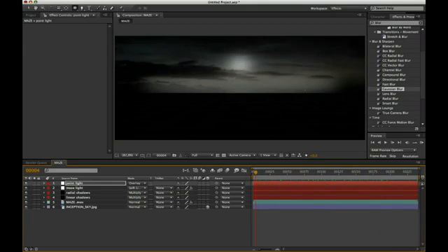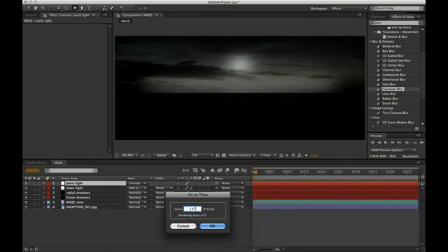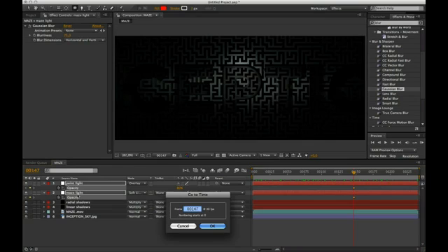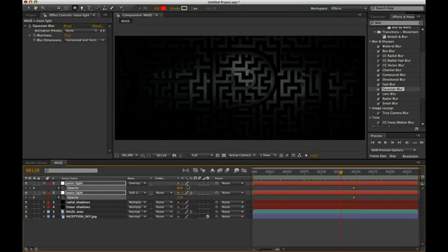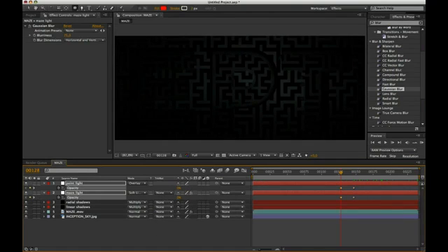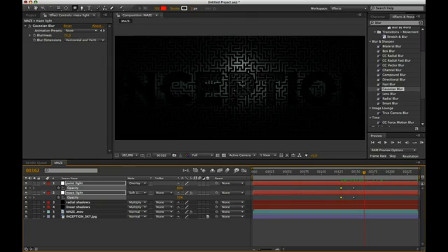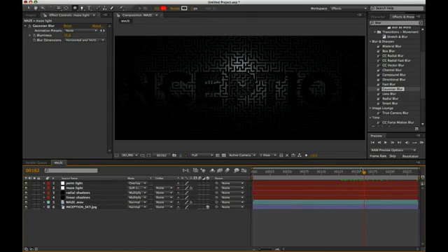As we can see, the two lights at the beginning of our animation must not be present. Go to 147 frame, and activate the opacity values already set. Go to 128 frame, and set both the opacity to 0. OK. If you want to give a darker effect to the logo, you can decrease the intensity of light.